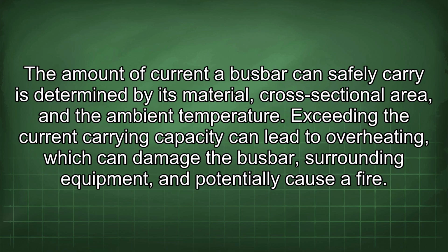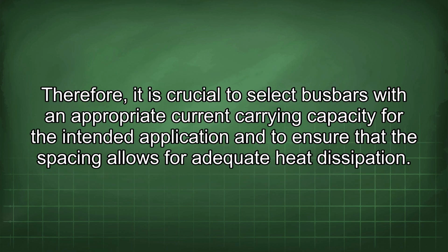One of the primary considerations in busbar spacing is the current carrying capacity of the busbars themselves. The amount of current a busbar can safely carry is determined by its material, cross-sectional area, and the ambient temperature. Exceeding the current carrying capacity can lead to overheating, which can damage the busbar, surrounding equipment, and potentially cause a fire. Therefore, it is crucial to select busbars with an appropriate current carrying capacity for the intended application and to ensure that the spacing allows for adequate heat dissipation.